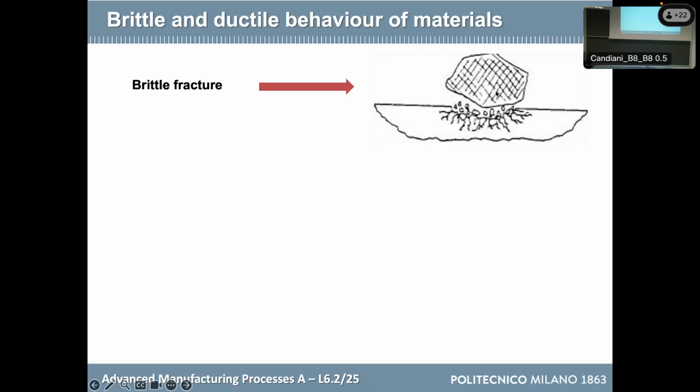So the grain of the abrasive is coming from the top and it is hitting perpendicularly. If you think about the action of the wind against the mountains, the wind is taking particles and hitting the vertical wall of a mountain, and after many years, it can dig even the rock. Here we are just accelerating this process, and we are using water instead of air. And so, in other words, if I want to remove more material on fragile target materials, it is better if I hit perpendicularly.